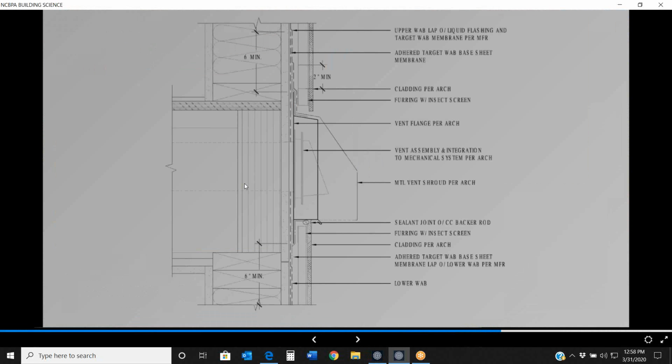When we look at HVAC penetrations, or any penetrations really, a lot of times the thought is, okay, we've got our air barrier coming through, we've had to put a duct through it, I can seal around that duct, as you can see, kind of with the green line that goes around the HVAC. But in reality, the air barrier now comes into the building. And this is something that mechanical people have known very well, is that when we tie into these kind of mechanical systems in our ductwork in a building, all of the joints in the ductwork and all of the equipment are now part of the air barrier. So how do we manage that? Making sure that we're sealing these things kind of as a whole building and not just out on the facade or out on the sheathing as we're looking at our design.